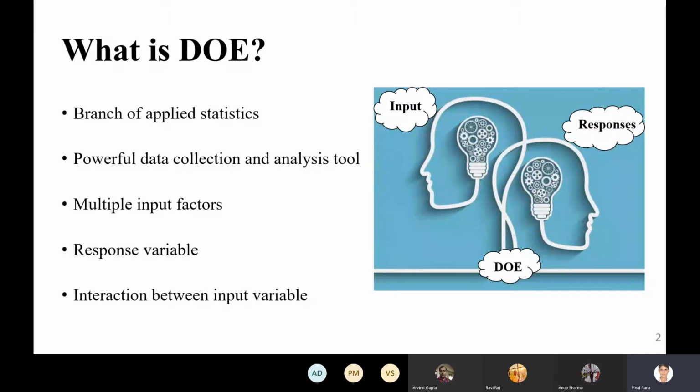If we take an example of a laser, then laser power, pulse duration, frequency, fluence, and a lot more other input parameters, whereas the temperature obtained at a different time and space is considered as an output or a response variable. So by manipulating multiple inputs at the same time, DOE can identify the important interactions that may be missed when experimenting with one factor at a time.